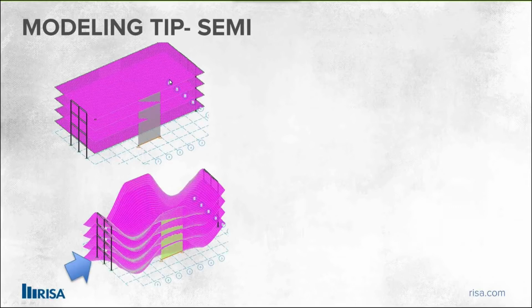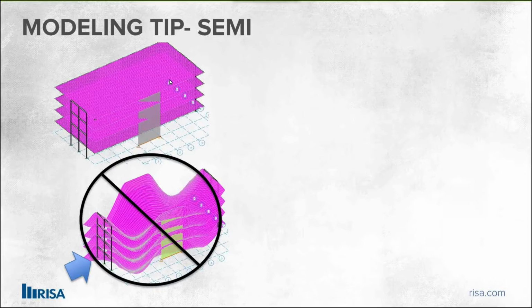And what happens is when you start applying those lateral loads, so wind or seismic, there's nothing to keep that slab stable. You put that lateral load directly into that deck, or whatever you're modeling there, without any vertical stability. Now it has some out-of-plane and in-plane stiffness, but it's not fully rigid like we were talking about prior. So you end up seeing a model that looks like spaghetti on our screen. So it's really important to say, hey, that's probably not the greatest method to model when you're using a semi-rigid diaphragm. So I have a big don't do that.